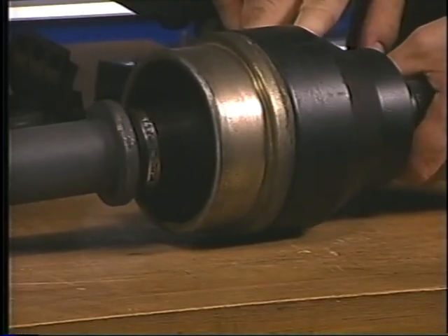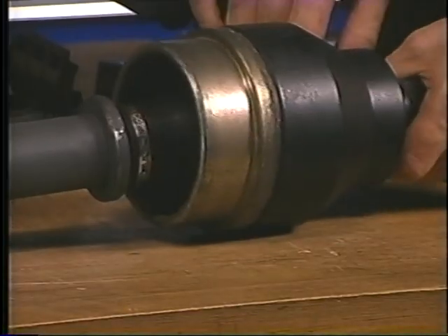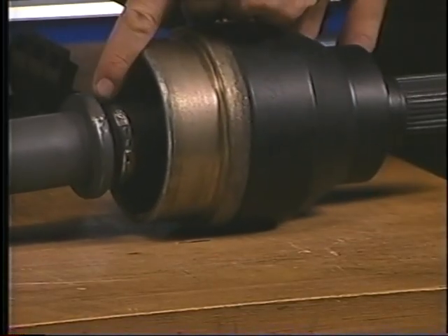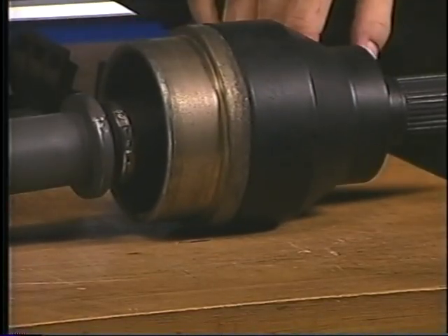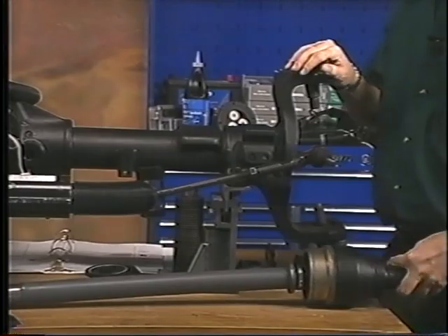So look at that. You may wonder, how do I service that boot right there? How do I replace the boot? Guess what? Don't. If that boot has a rip or a tear in it, you got to replace the whole unit, the whole quarter shaft. Comes with a new CV boot right there. Now, we want to talk about a couple of seals.